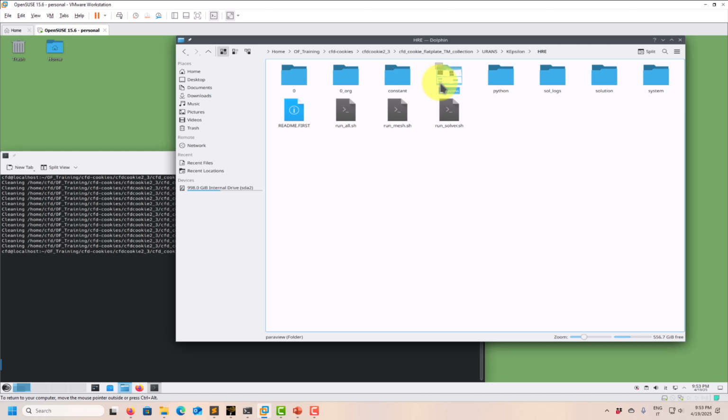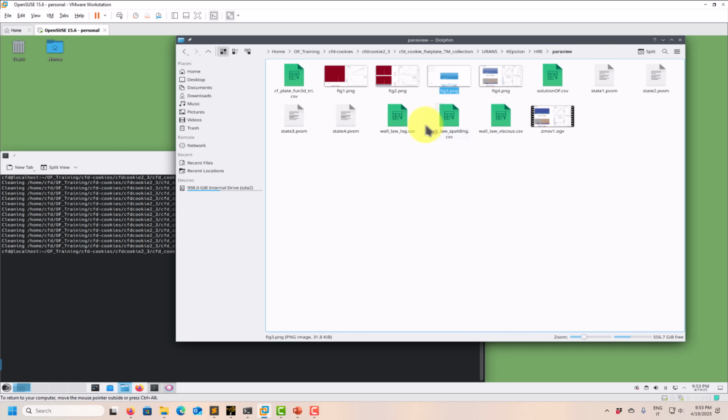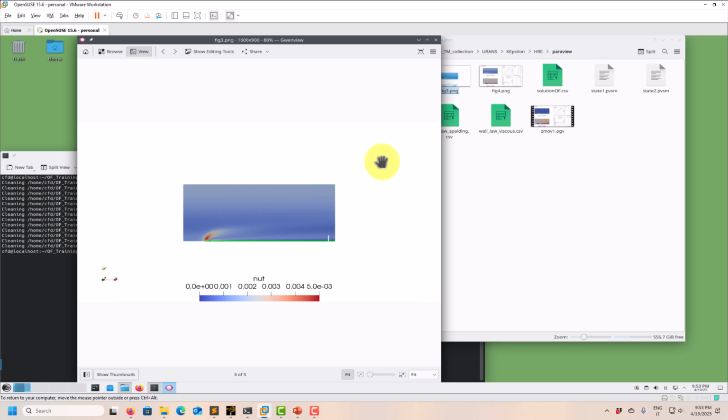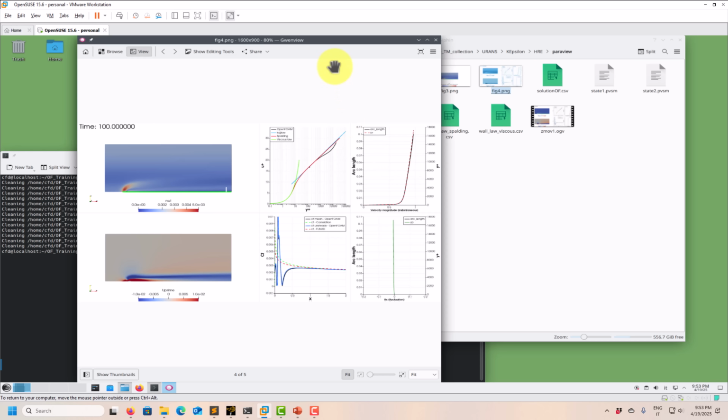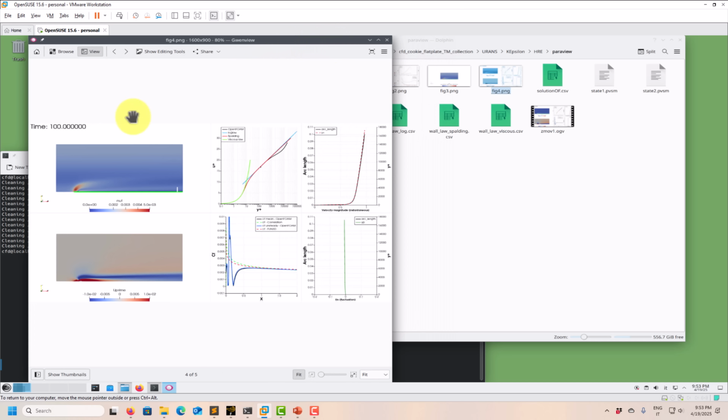Okay, so Fig 3, this one usually we have the friction. Oh, okay, this is 0. I need to redo that. I'm quite sure that I will forget that, so that will stay here until the end of time. So look at what we have here. Clearly you can see that K-Epsilon is completely averaging, smearing, or erasing those fluctuations. Look at that, this is a very uniform behavior, okay?